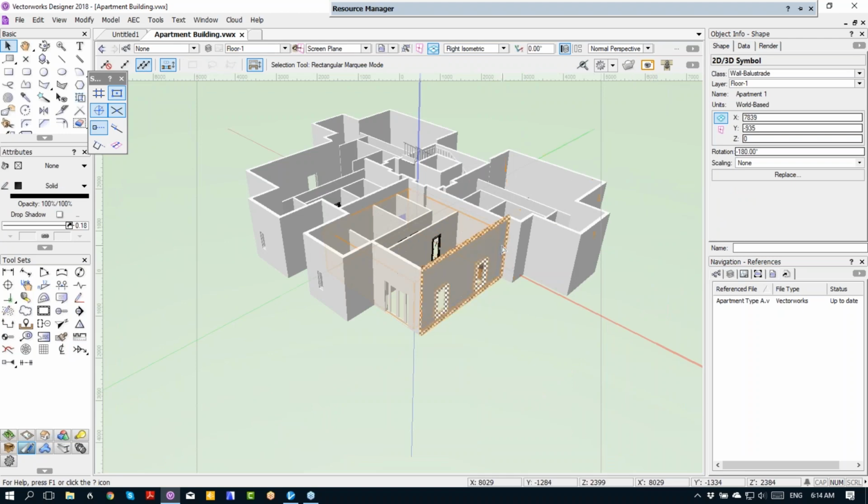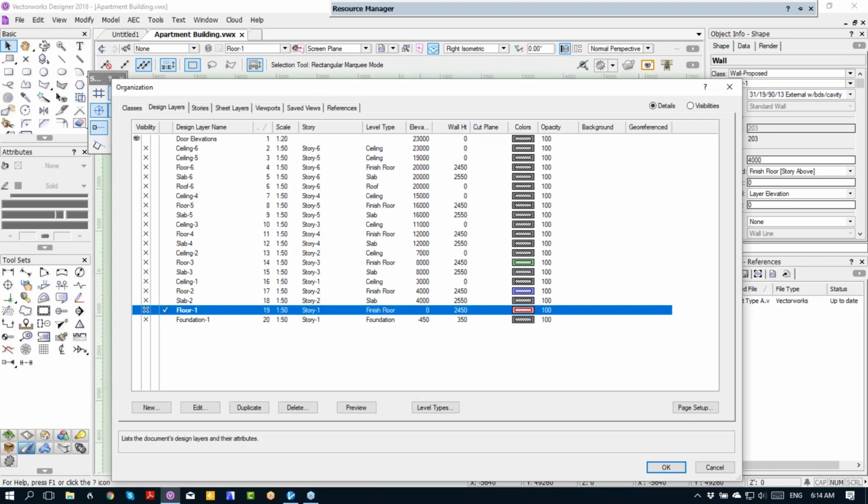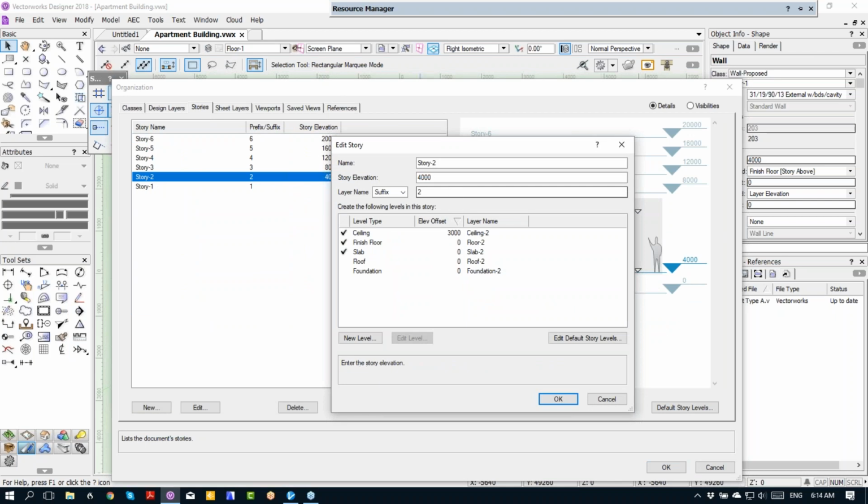But why then use the stories and the walls connected to the stories for the rest of the building? Well, because I thought that gave me quite a lot of flexibility and quite a lot of speed at creating the design that I wanted. Because these are connected to my stories, if I change my stories, so let's go back and do that properly this time. Working on floor 1, let's go to our stories. We'll change this one. We're going to make that 16 feet.